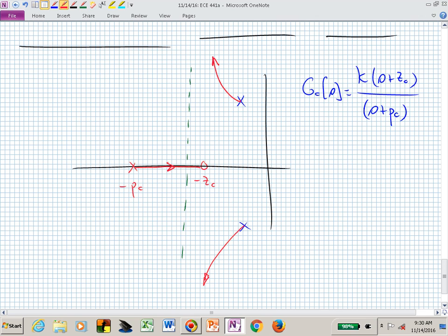And then you would pick closed loop poles to meet your settling time spec. So let's now say this is sigma sub A, and this is the settling time spec. So we have all sorts of lines flying around, but we need to keep them straight and understand how they might help us in this design process.